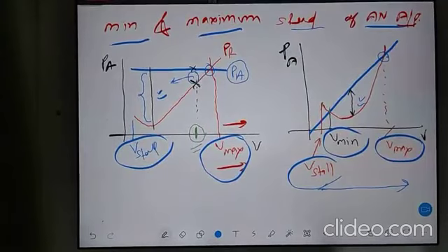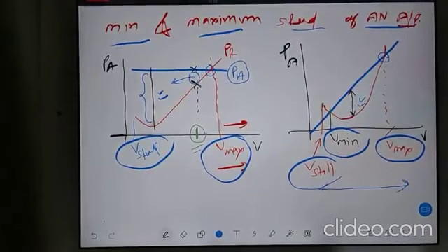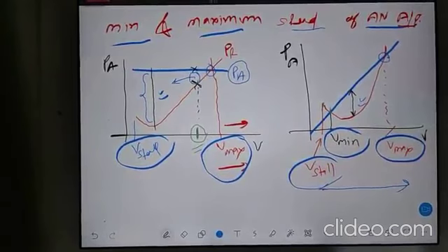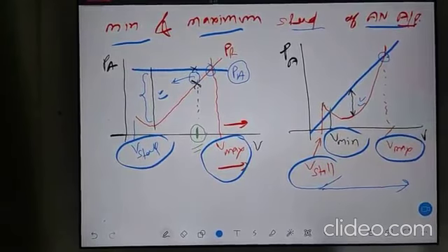Copy down. So you got one idea that whether you talk about a piston engine or a jet engine, the maximum flight speed you can easily determine by the intersection point. The moment when power required and power available are the same, that is your maximum speed. In the same way, you can also talk about the low speed of the aeroplane. How will you get it? And stall speed, how will you get it?